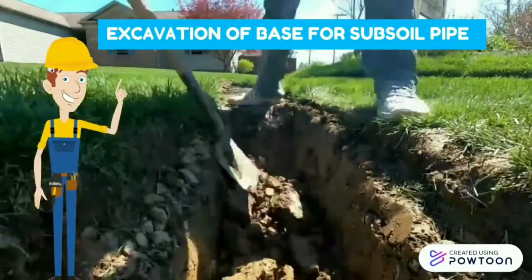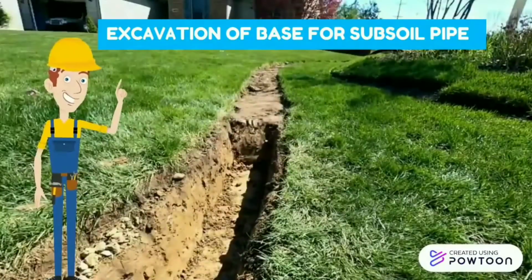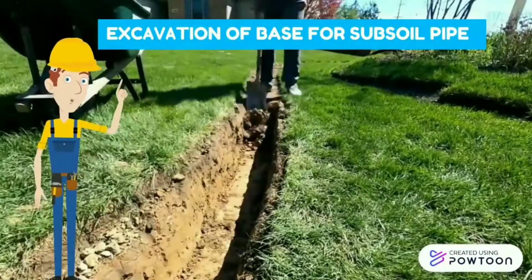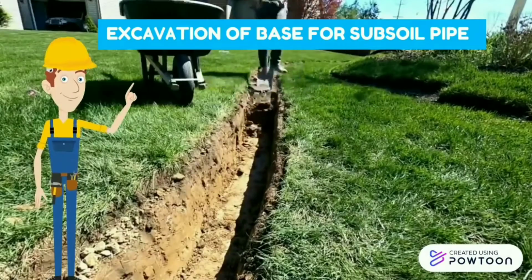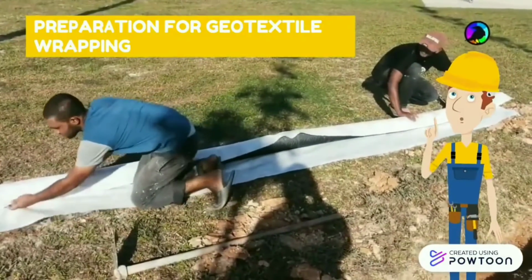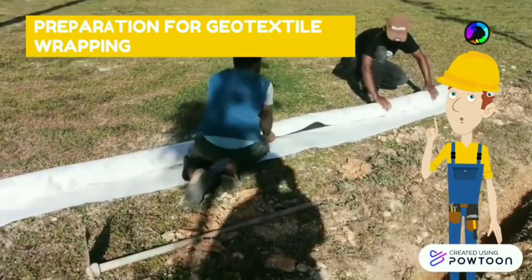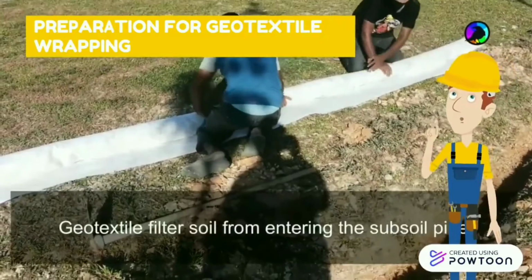First, excavation of base for subsoil pipe. The depth of a subsoil drain is determined by the groundwater conditions, the amount by which the groundwater level is to be lowered, and the available hydraulic gradient. Next, preparation for geotextile wrapping. The pipe can be wrapped in geotextile to prevent piping and loss of filter material.